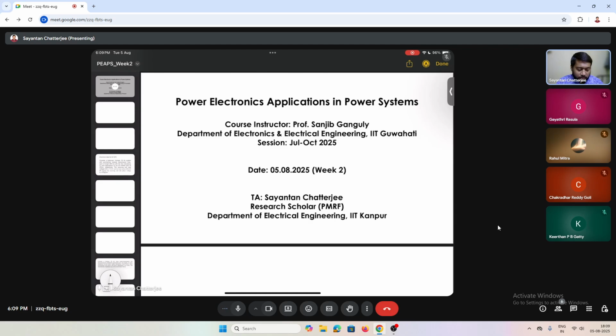With this, the transmission line that we majorly see is typically classified into three segments: small, medium, and long. The short transmission line, or smaller transmission line, is based on length less than 80 kilometers, the medium is from 80 to 250 or 240, and more than 240 to 250 kilometers we consider as long transmission lines.